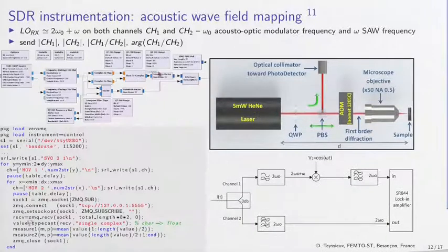So this brings us to the actual signal processing flowchart. We have here the USRP source of the B210. Because we wish to get rid of the noise that we have just addressed of the phase measurement, we have these two frequency translating FIR filters acting as heterodyne measurement, and we will display the complex to magnitude.